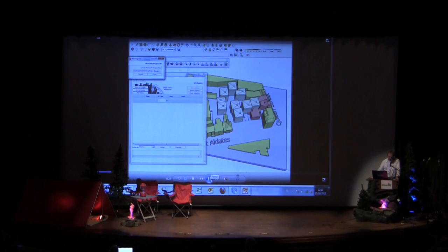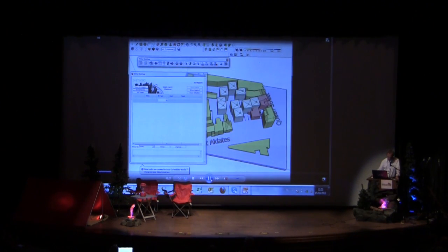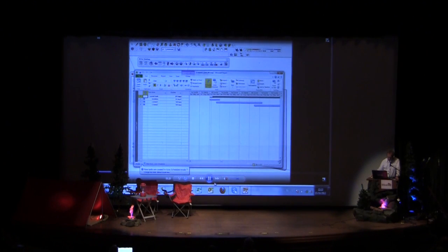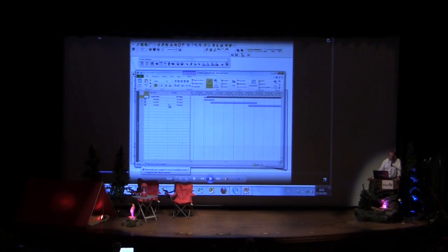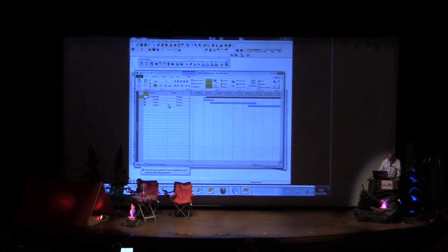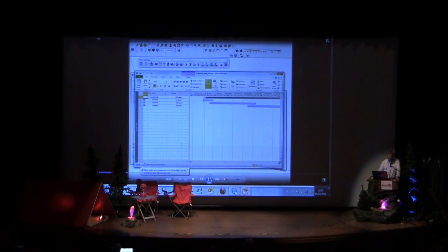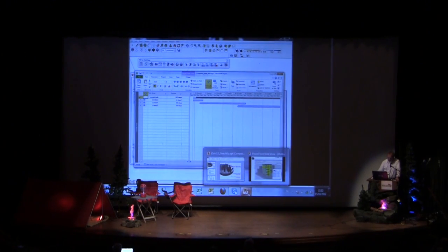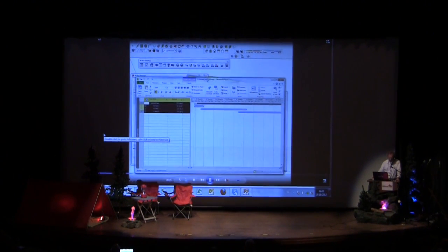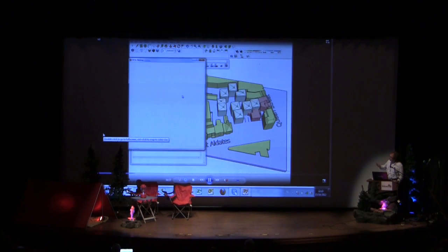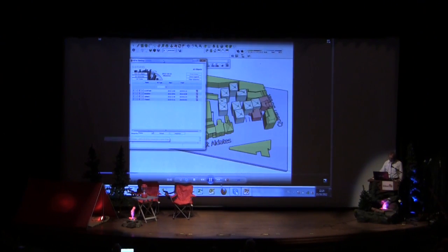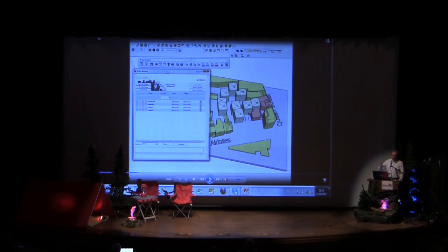So I open up an MS Project file, which also functions with P6 Primavera and with Power Project. You can see here it's a very, very limited schedule just to show the principles of functioning of this model. I've got 4 tasks, 1 demolition task, 2 construction parts, and an environment which has to be kept all the time. So what we do, in this case, we select all the information in all the tasks we want to select, and we link it to our SketchUp model.